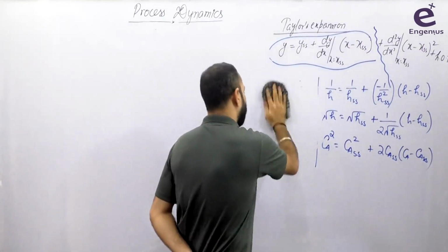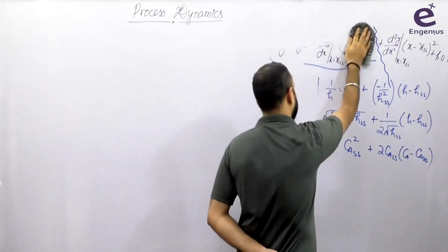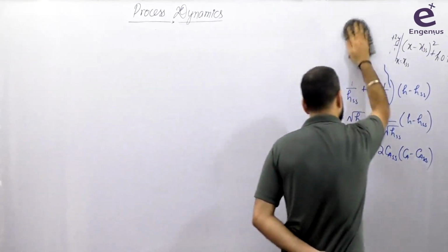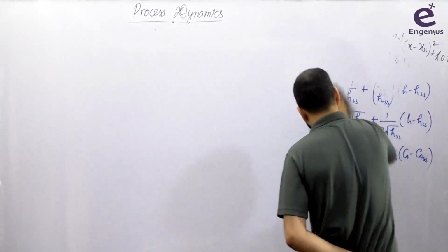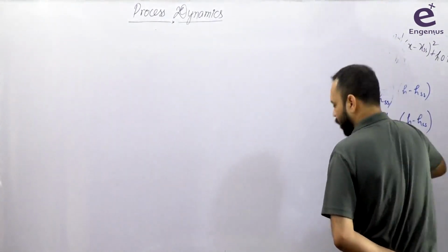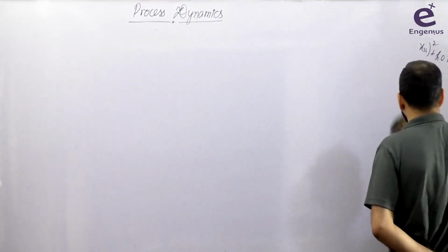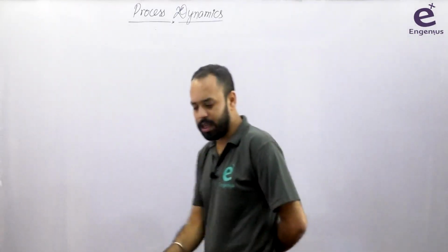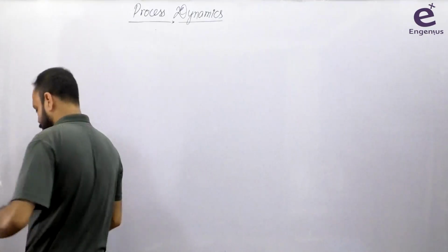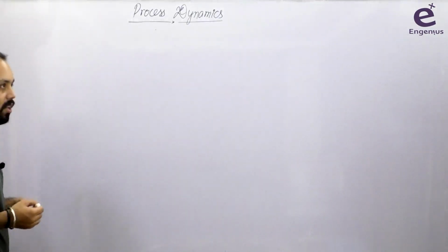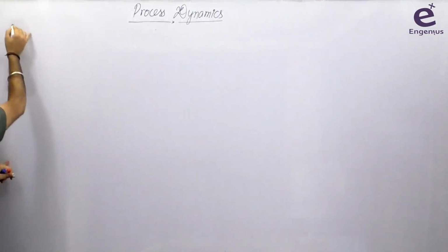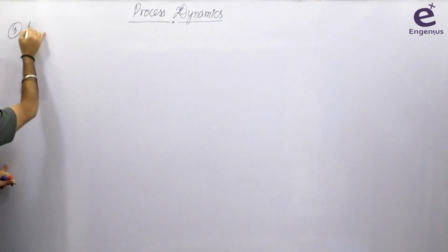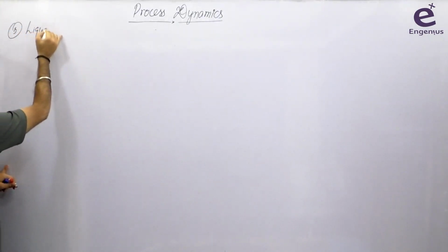The output variable, input variable, the function of time, nothing is going to change. The only thing that changes here in this system is that the relationship between Q out and height of the system is not linear. This is a very common standard question for practice of GATE, right? So I think this was the 5th model. Fine, that is the liquid level system.